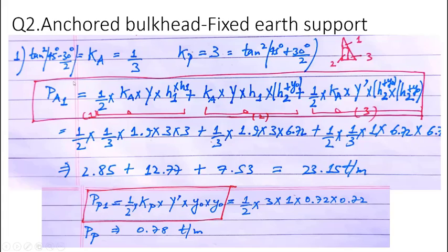So the total active pressure comes out to be the summation of these three. So first calculate this one. One is what? One is half base times height. So half base, this is the stress Ka gamma H1, and the height is H1. Then the rectangular variation, Ka gamma H1, this is the stress.